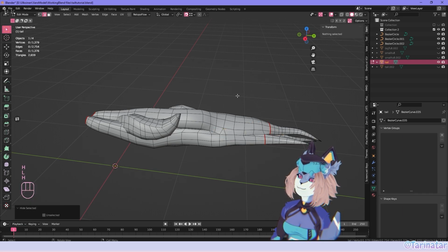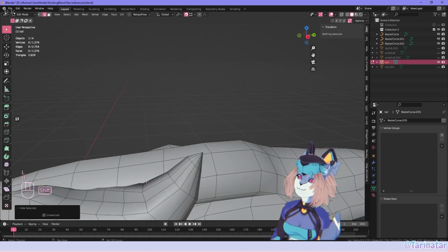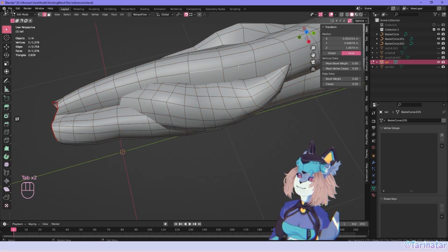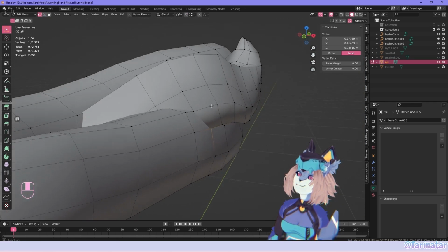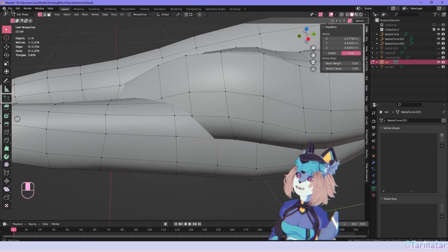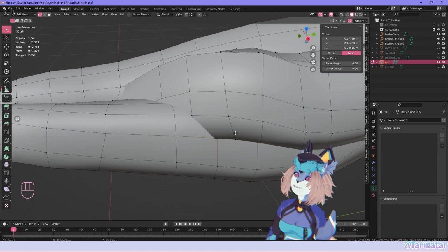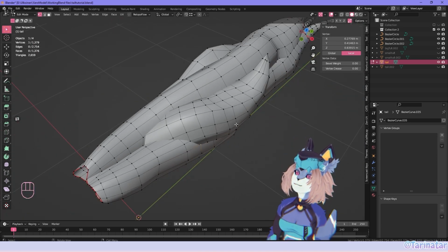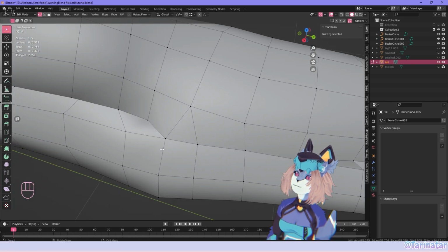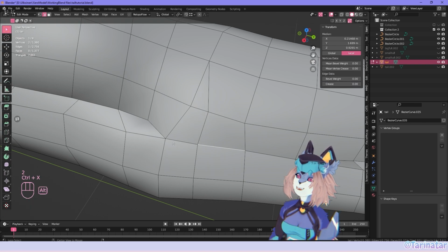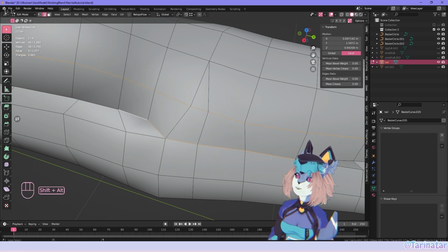So we are gonna hide everything but one of them, and we will make a hole in the main part for this one. I'm making a spot for it where I plan ahead which vertices, and while I do that I will again be seaming the meeting points. Generally, if you want this part to have a good flow into the other object, you don't want triangles on the meeting points. So like here, how we have a triangle here, this would not be good. How we would fix this is by extending it into a square and here have the triangle. So we have a clear loop here without triangles.